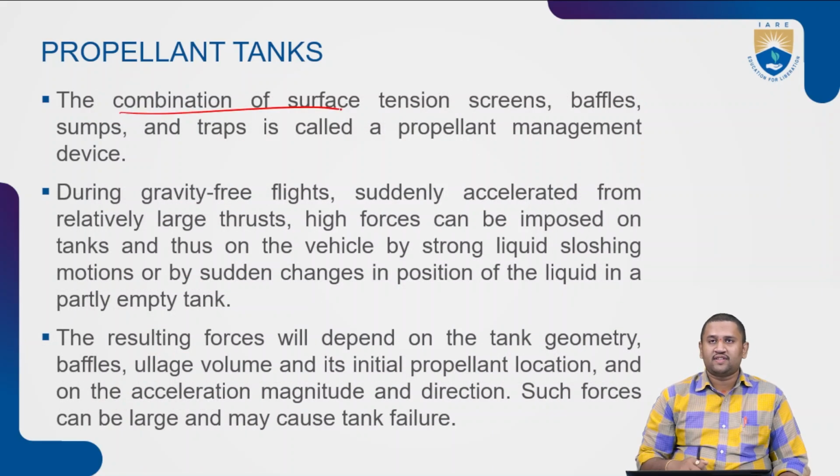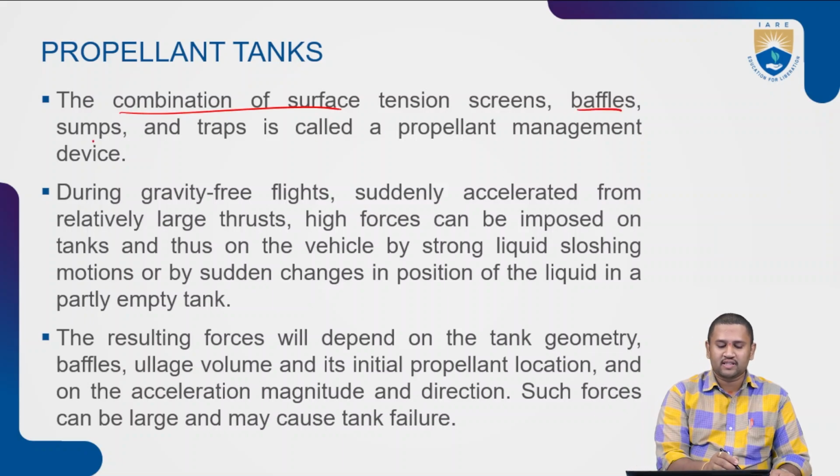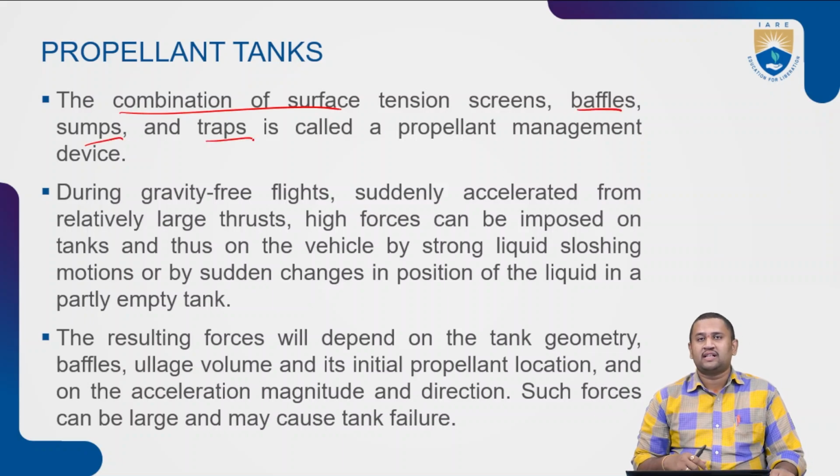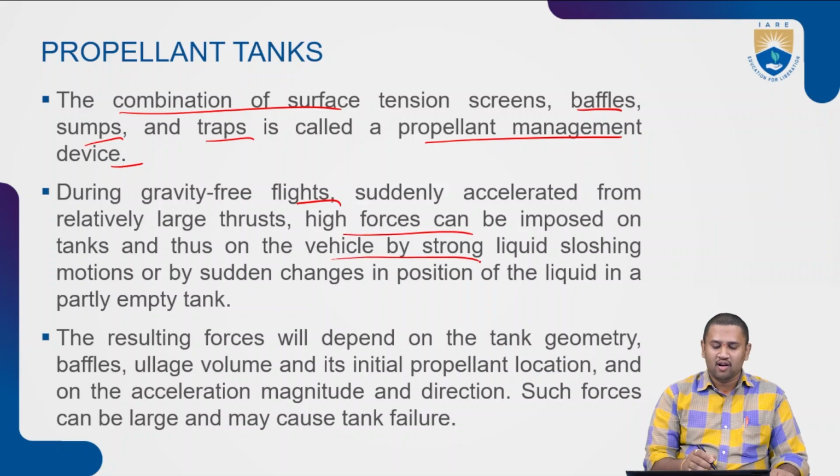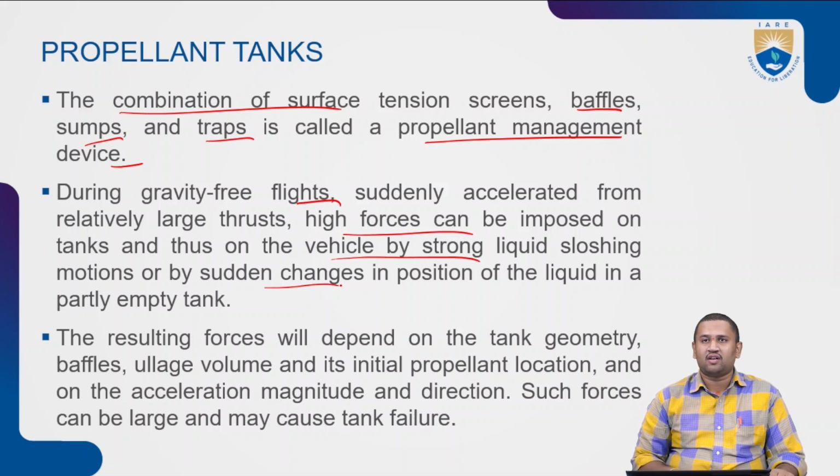A combination of the surface tension forces, particularly screens, baffles, sumps as well as traps, is called propellant management devices. During gravity-free flights, when suddenly accelerated by a relatively large thrust, high forces can be imposed on the tanks, and thus the vehicle, by strong liquid sloshing motion or by sudden changes in position of the liquid in a partly empty tank.